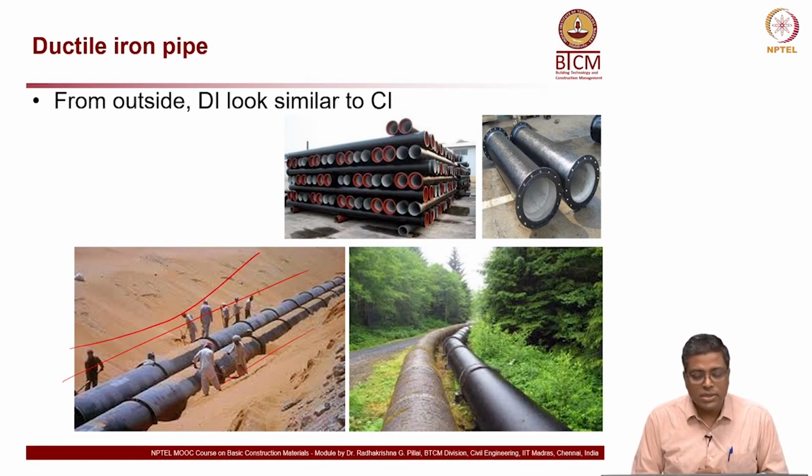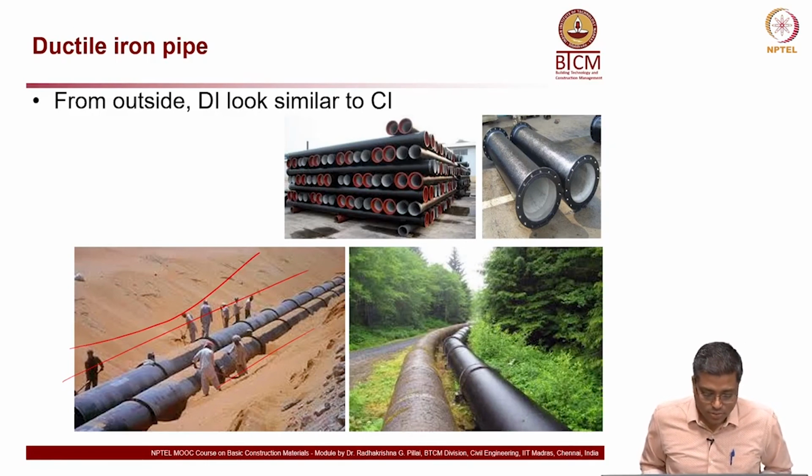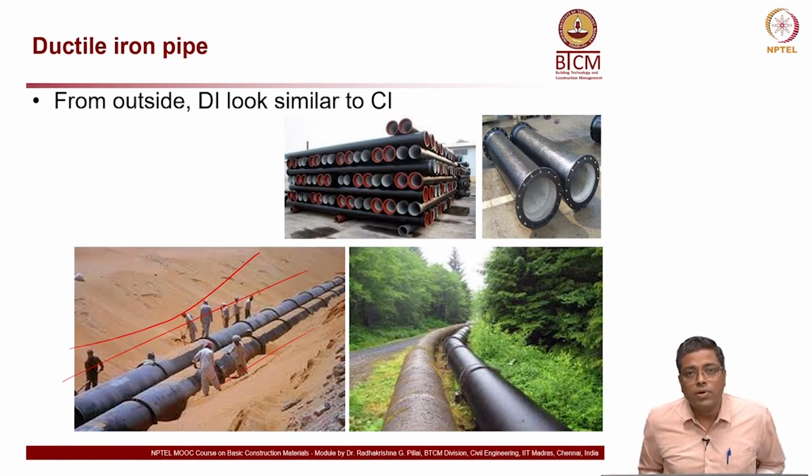So, nowadays you will see that ductile iron is more preferred than cast iron products, especially when you talk about possibilities of deformations. Okay, and you want structural systems like even these pipes to deform but not crack. Okay, so that's the idea. Deformation is okay, but it should not crack, and if it is cracked, the liquid which is flowing through will leak. So, that we do not want to happen. We want ductile structures and we do not want structures to be very brittle in nature.